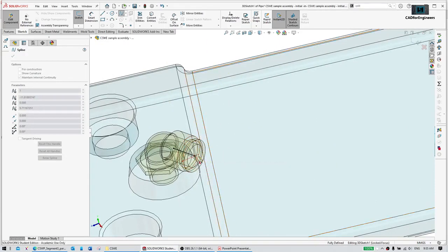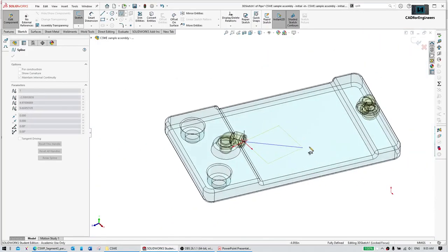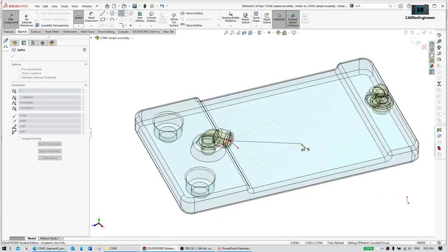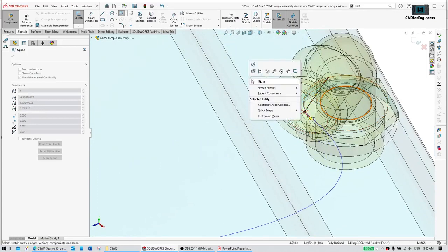Okay, I'm gonna go ahead and select this line. The plane is YZ. Just check the letter, it is ZX. Okay, so ZX means you're on this ZX plane, so this is fine. I'm gonna go ahead and just connect to this point. Just right click and select.